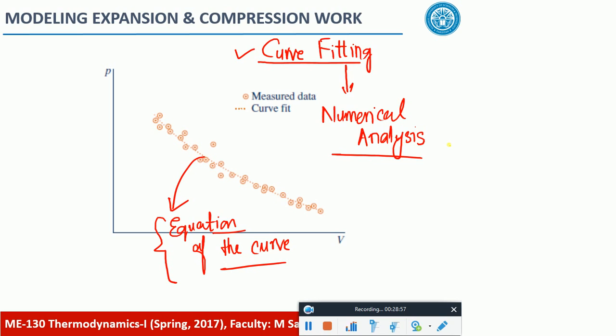No, not all the time. I'm explaining one terminology: how do you mathematically analyze those processes? The system is moving and still you are measuring its pressure and volume. How can you do it? The pressure sensor might be giving you a value after some lag in time. So this is not an equilibrium position, but still you are considering it as quasi-equilibrium, just to mathematically model this. Okay.